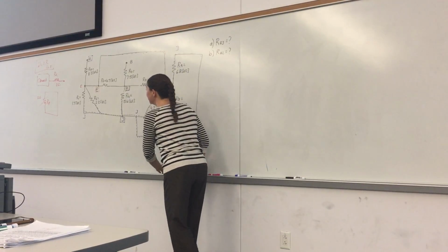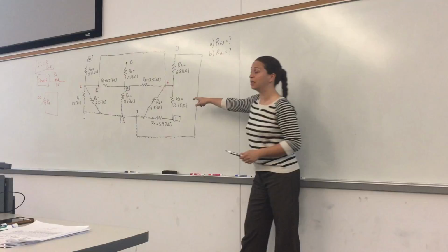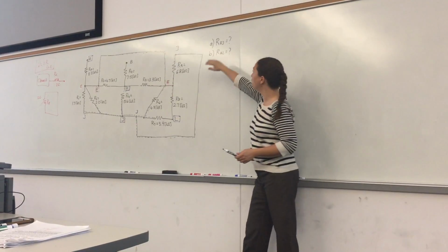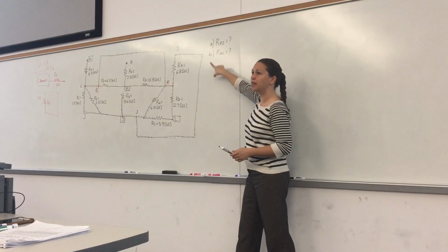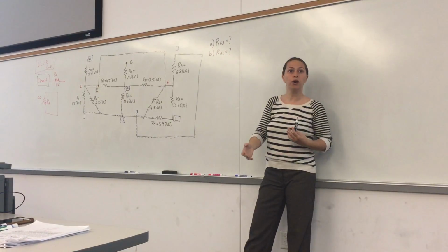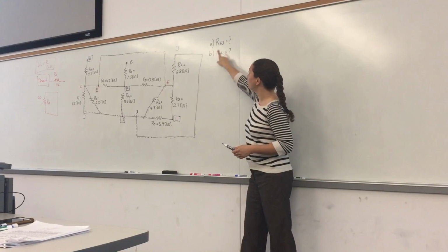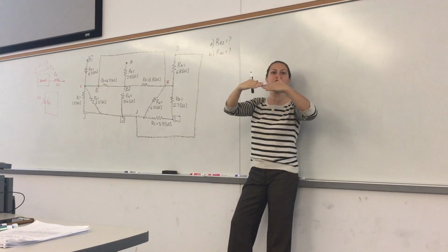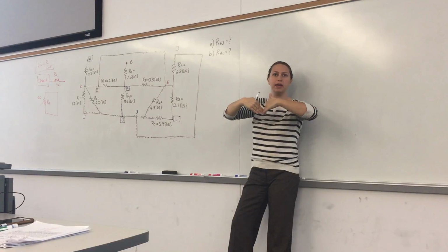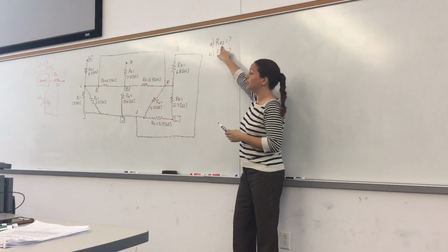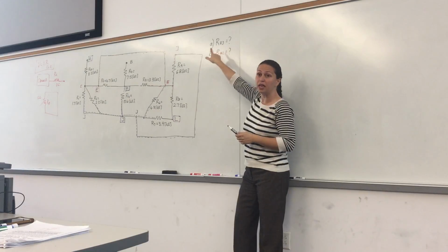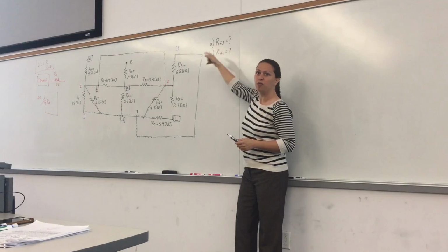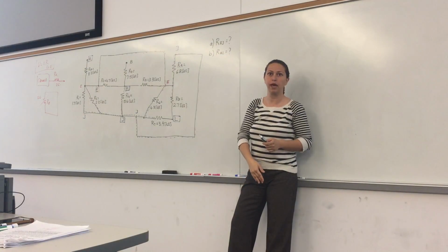Now, when you are doing this, it's important which two terminals you are interested in. So let's get part A first, and then we're going to look at part B. Remember, when you connect two resistors that are in series, the middle node is lost, right? When we are trying to find the equivalent resistance from F to J, we will pay attention not to lose one of those nodes, F and J. We can lose all the others, okay?